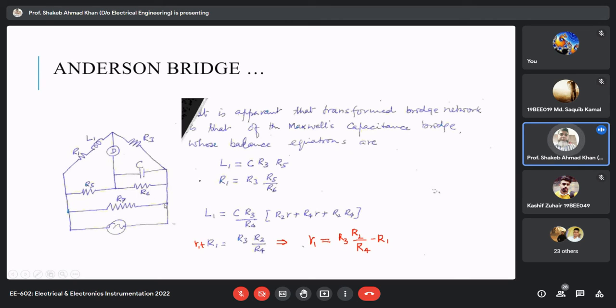If you look at this bridge, these two arms and these two arms, the five arm bridge is converted into a four arm bridge, and we are more familiar and comfortable with this. R7 does not have any role to play. This resistance is appearing across the supply.